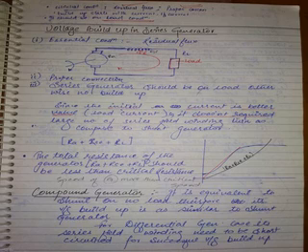But from no load to full load condition, what is the voltage across the generator? Is it constant or varying? From no load to rated load. Let it be somewhere here, the rated load. In this region, what is the voltage across the series generator? Is it constant or varying? It is varying. It is a variable voltage generator. It has rising characteristics. This is not suitable for normal power supplies.